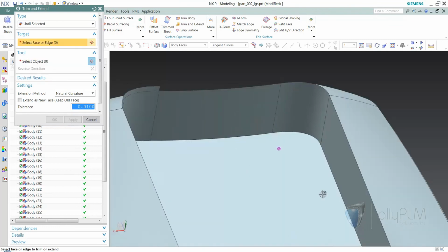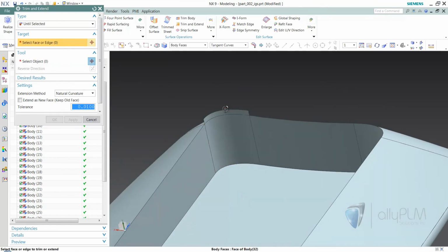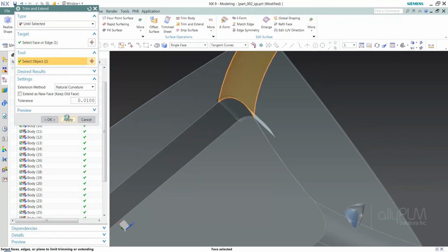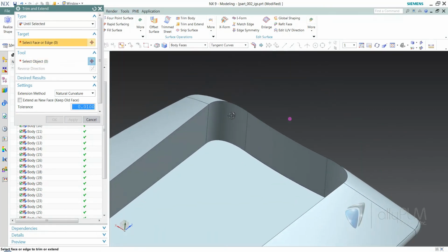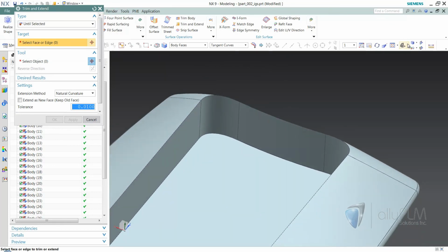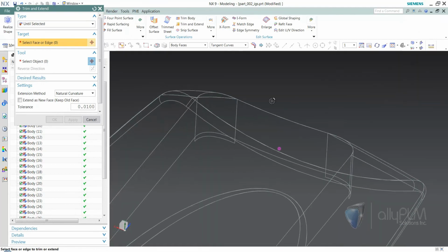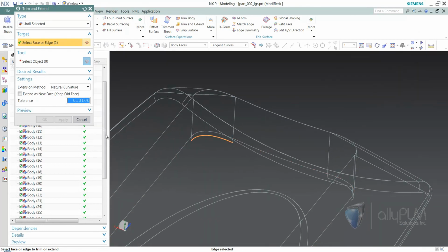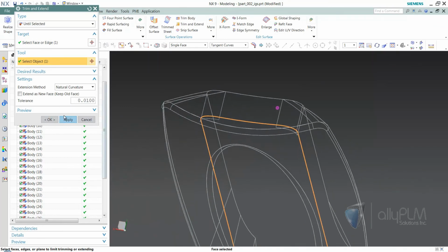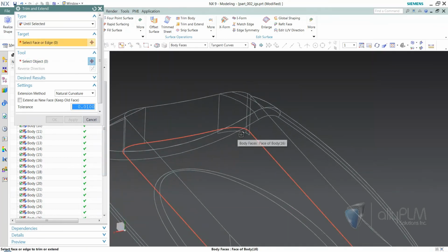So go ahead and apply that. Select this top edge, and we want to make it even with this other connecting surface. Now I'm going to need to change my model to maybe a static wireframe so that I can pick the edge at the bottom, and then that needs to be trimmed to the bottom of this pocket. Same thing on the other side.